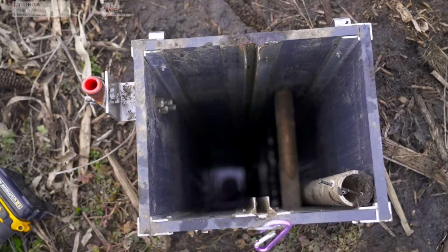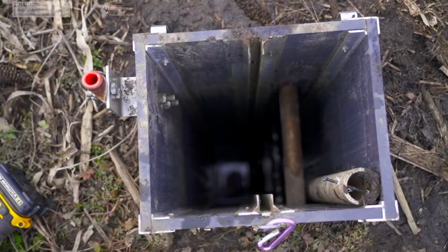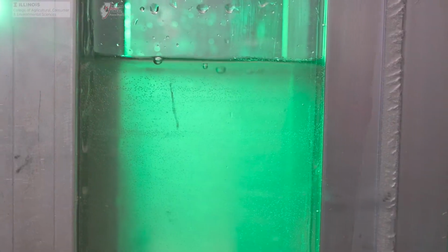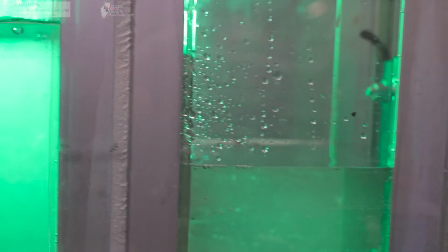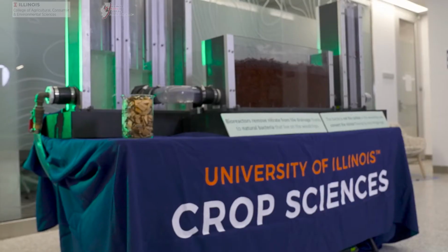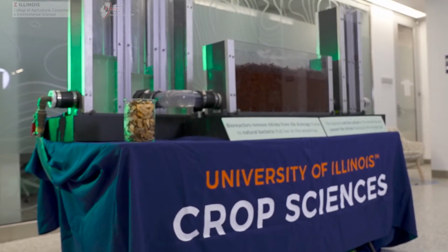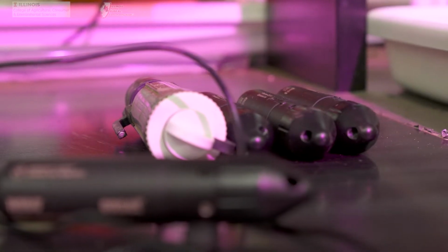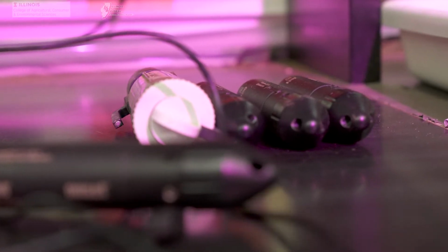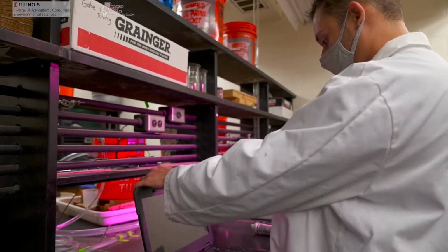The sensors record the depth of water, essentially the depth of pressure pushing down on them. We can relate the depth of water logged by the sensor in the control structure to a specific tile drainage flow rate moving through that structure. We start this process in the office because these sensors need to be launched from, or essentially set up on, a computer.